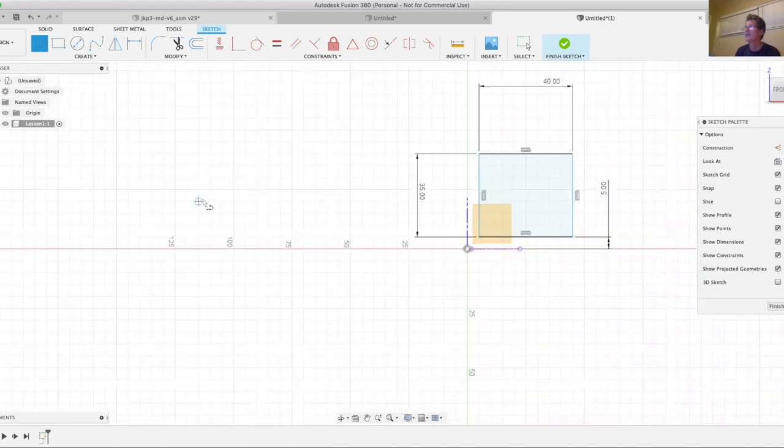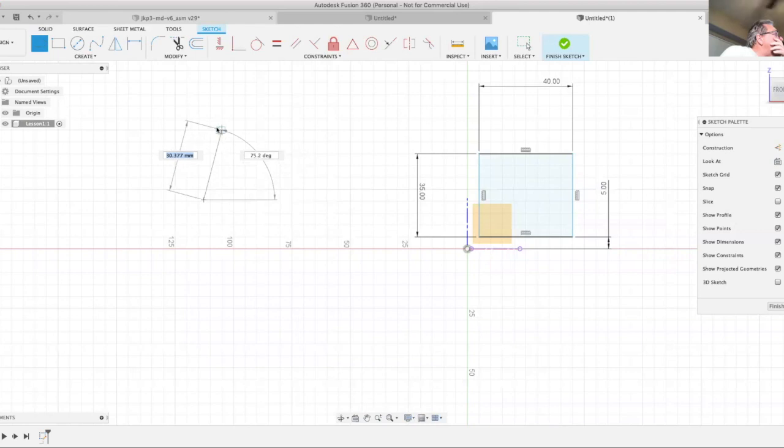Now, if you start drawing a line, so you click once and then move, as you go towards finding the second point of your line, there's various assumptions it will make as you get close. So if I get close to vertical, it's going to snap to vertical, and you see the little marks there that indicate that it's making an assumption, the little sort of feather marks.